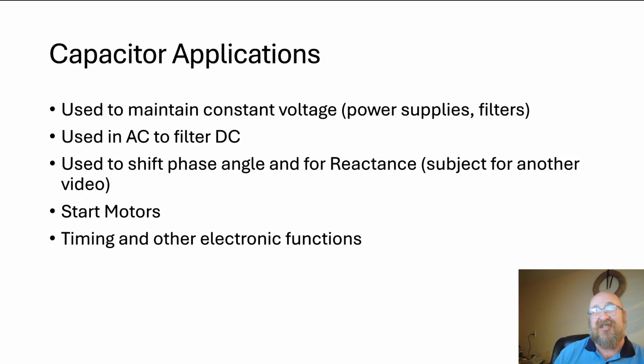It's also used to start motors. So when we get into talking about motors themselves and how they work, three-phase induction motors are pretty easy. They don't really need a whole lot of help getting started. However, if we're doing single phase, it's going to get a little hard to get it started rotating. Once it's rotating, it works pretty well. But getting it started, we need a second set of fields, and we need to energize those fields.